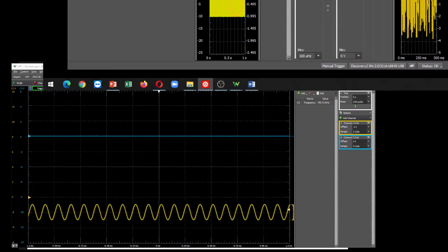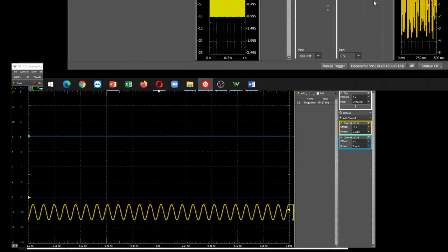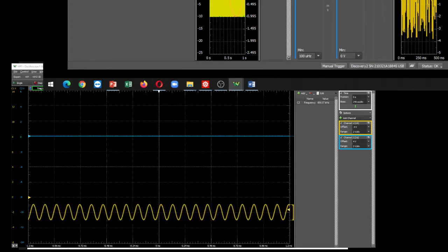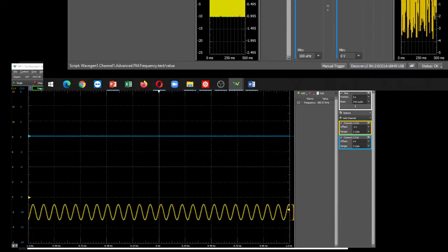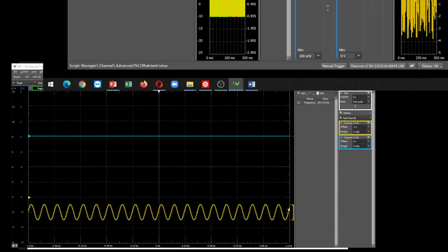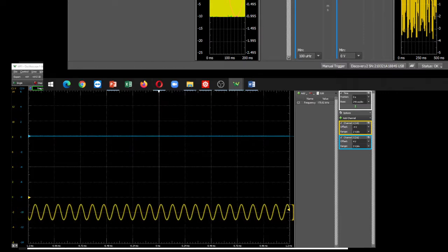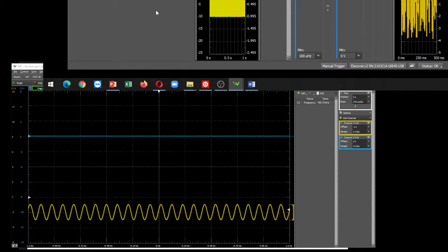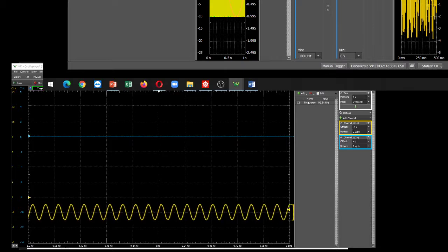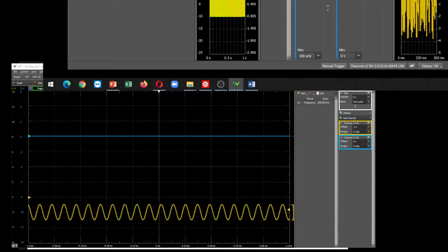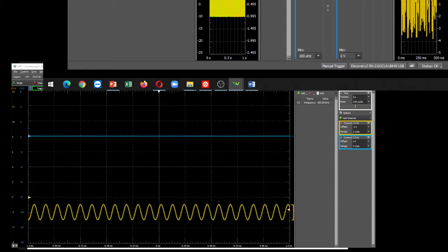Here is an illustration of frequency modulation. The amplitude of the carrier is constant, not modulated. Its frequency, however, is not constant, but shifted by a small amount, proportional to the message signal amplitude. The demonstration here shows a very slow rate of frequency modulation so that it is easier to see on the scope. In real applications, it is modulated at the data or signal transmission rate, which can be very high, up to a fraction of a percent of the carrier frequency.